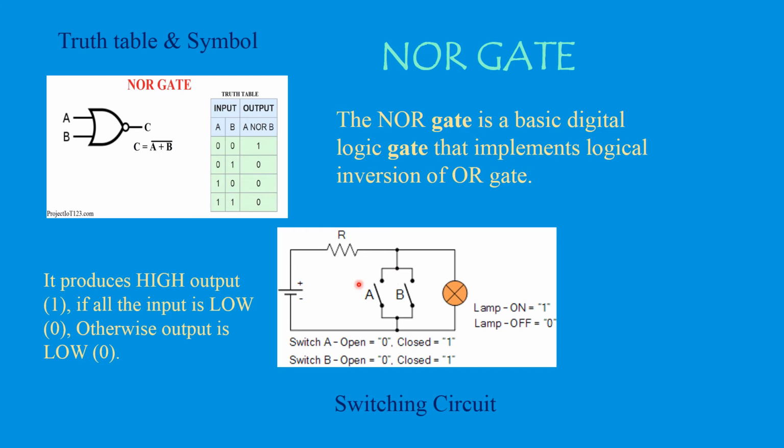So now going for the explanation, making all your assumptions as I told you earlier, we'll go into it. So what are the cases available? When both my inputs are low, my output is high over here. How is it possible? When both my inputs are low, that is, when both my switches are open, this path will be an open path. So in other words, on the whole, this will be a closed circuit. As soon as I supply, all your electrons will be flowing through this path and a voltage drop will occur because your lamp will be glowing.